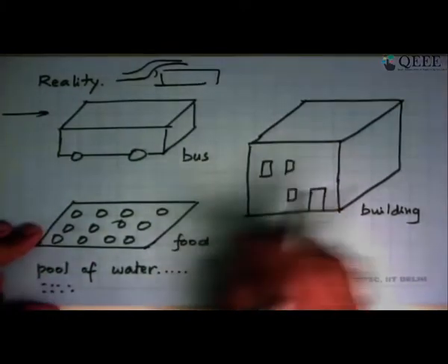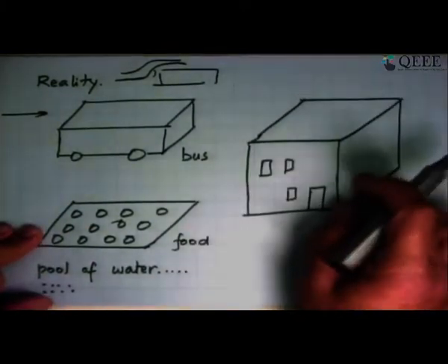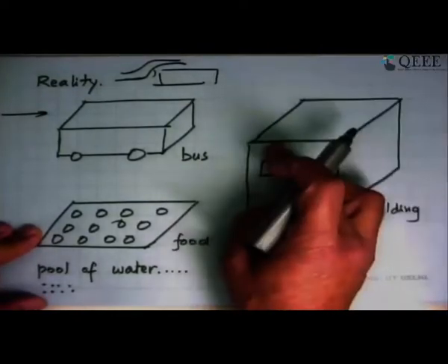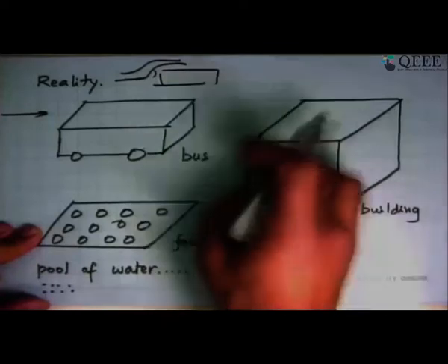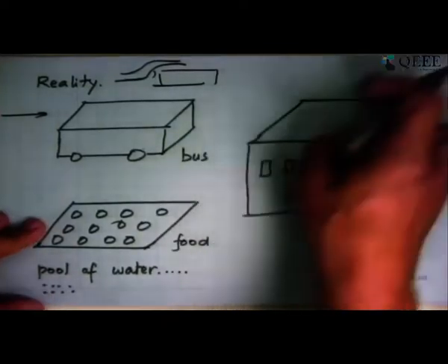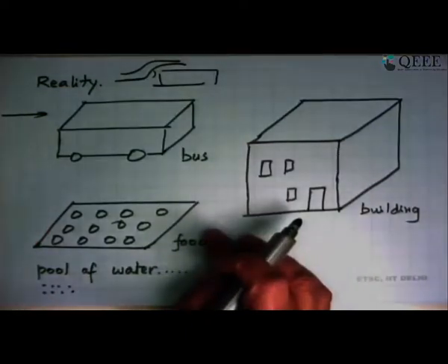Now I'll calculate the heat transfer. Similarly, we do the same thing for the building, with the roof or the side, and say that air is coming on top of this. We ignore these things and say, look, at the first cut, I will take this to be a flat plate on which air is coming. I will get an answer. It won't be an exact answer, but it is the order of magnitude of the answer that is of concern to me. Is it 5 kilowatts, 10 kilowatts, 100 kilowatts, 0.1 kilowatt? That number I will at least get a feel for. It's not the exact answer.